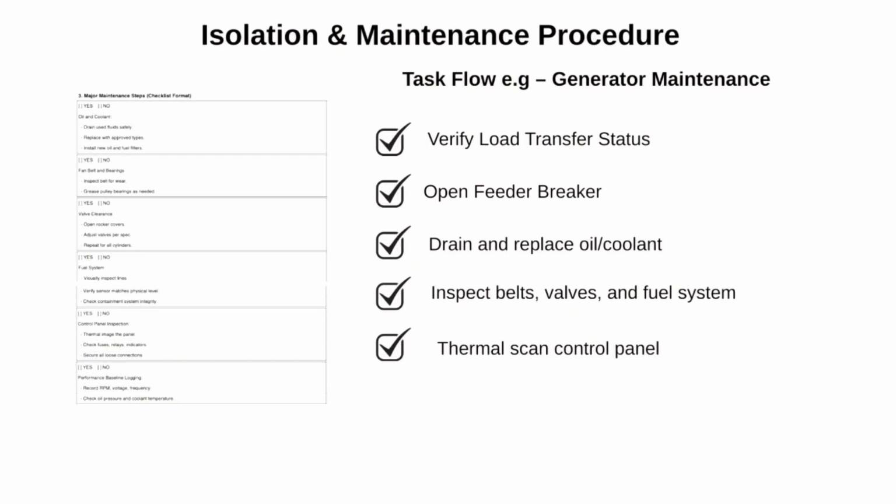Drain the oil and coolant. This step is just like with any engine. You want to remove the old fluids so you can refill them with clean, fresh ones. But here's the catch. These generators are huge, so you need spill kits, buckets, and sometimes even pumps. And yes, write this into the MOP. Don't assume people will just know.